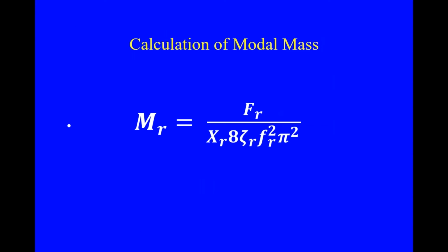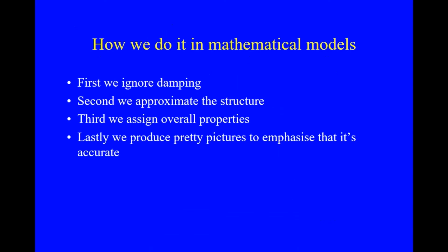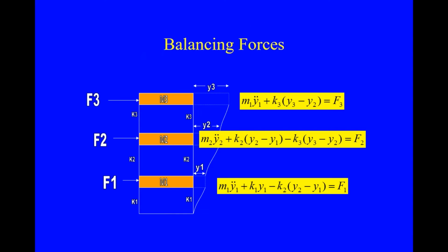So we've got different forces, Newtons peak to peak here. We've got the frequency varying with amplitude. We've got that amplitude there, differences from 0.65 up to 2.68 millimeters peak to peak. And then we measured damping. And in this case, it varied between 2.23 and 2.40.